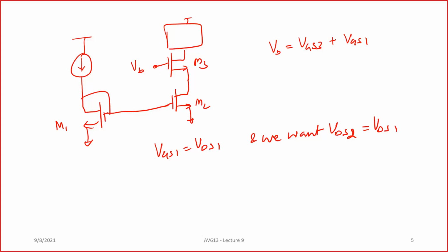Now, the first simulation that I did, which is ID versus VGS. What I would want you guys to do is to take that plot, save it as a CSV file, or you can read it in Excel, and store it, so that you will be able to reference it.